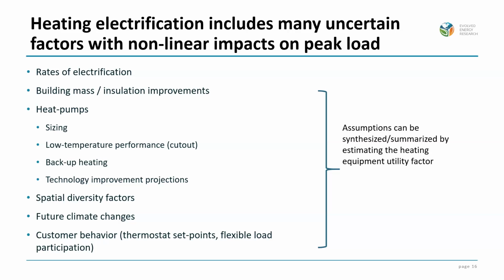Now, one of the things you can do with a heat pump is you can actually oversize them, right? And that helps with peak load impacts, because it sometimes means that you don't have to switch over to electric resistance when you otherwise might, in order to maintain a set point in the home. But a larger heat pump is more expensive.